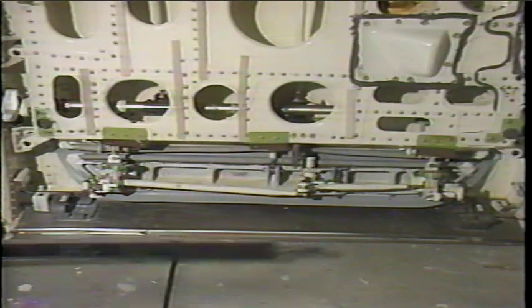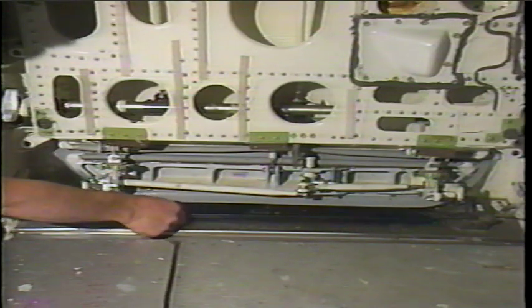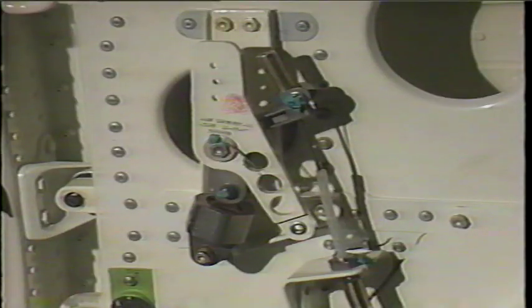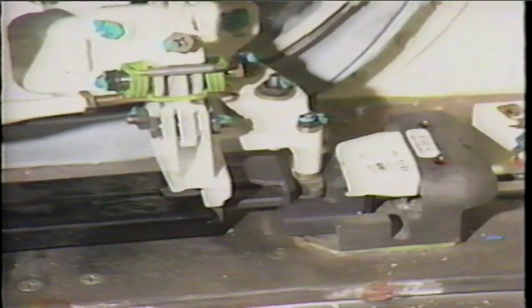Next, adjust the girt bar mechanism. The girt bar and girt bar sliders are positioned in the floor fittings. The position of the floor fittings is adjusted with the door mode selector lever placed in the engaged position. It should be noted that any adjustment to the latch cams will require checking of the girt bar, slider, and floor fitting alignment. Close and latch the door. Cycle the mode selector and visually verify the smooth engagement of sliders into the lifter and floor fittings. Reposition floor fittings on the inboard-outboard serrations for the smoothest engagement and disengagement.